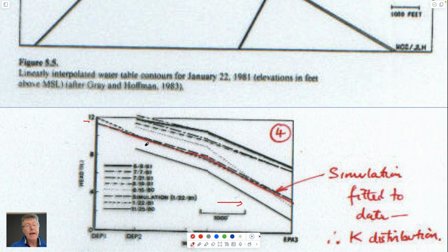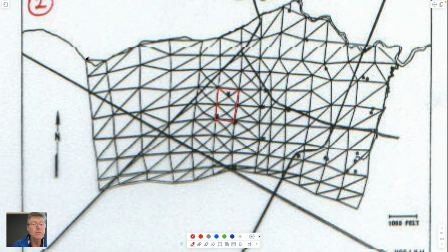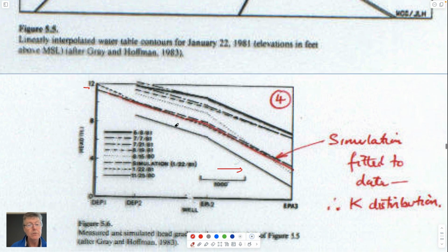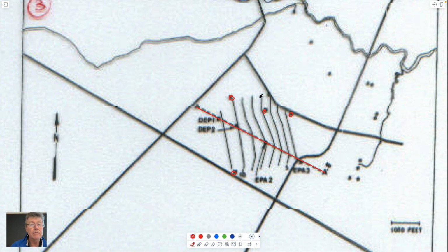And you run your model forwards so that when you run this model with some boundary conditions defined at the edges of this model, upstream, downstream, sides of the model, you actually replicate the distribution of heads along some section. And if you replicated the distribution of heads, you think you perhaps might have the right pressure profile upstream and permeability magnitude distribution. And so then you can recreate throughout the aquifer your flow regime. And so you've done this actually, right?